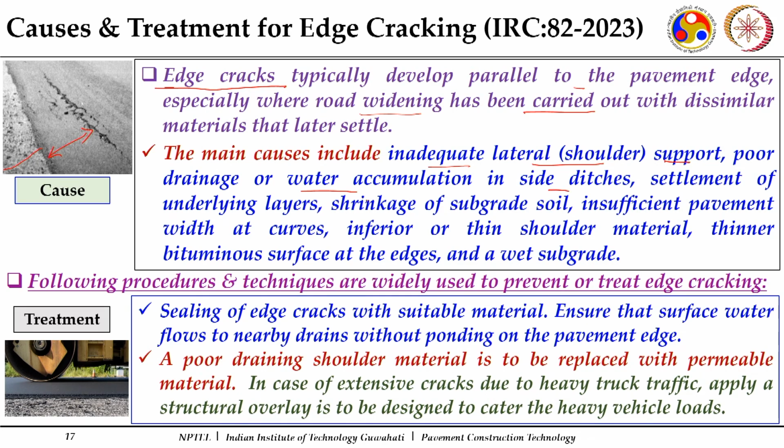Even if the drains are there, if they are not properly maintained and cleaned, then water stands in those drains. Settlement of underlying layers may also occur, specifically near the pavement edges. Shrinkage of subgrade soil or insufficient pavement width at curves is another cause.